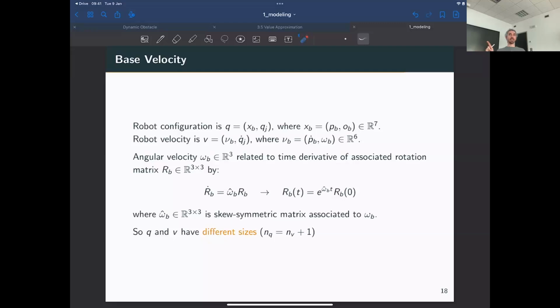And it exists also the quaternion for the 2D case, which is simply the sine and the cosine of the theta angle. So in 2D, the quaternion would be a two-dimensional vector, which always has norm equal to 1. So if you want to do things properly, even with a bidimensional wheeled robot, you should use these kind of tools.